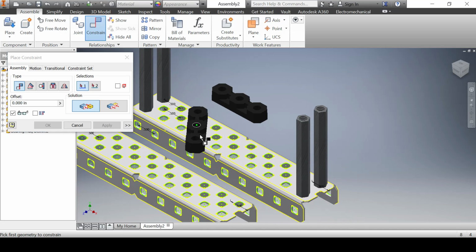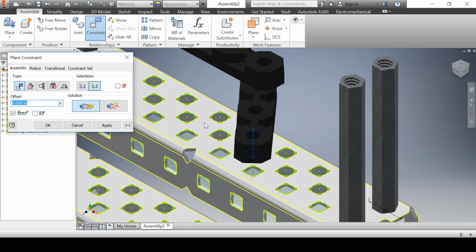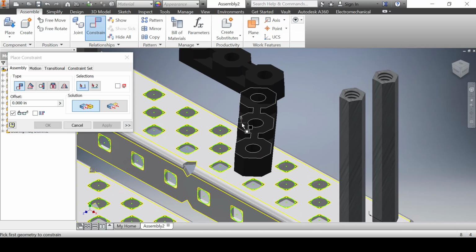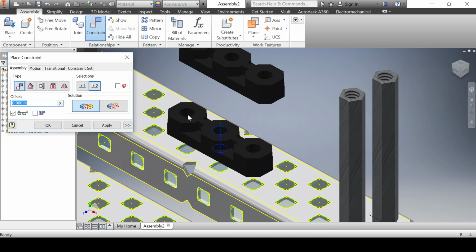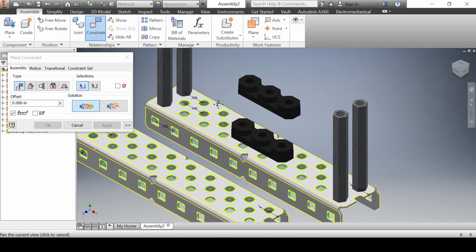Now clearly this is not the direction we want it. So what we do now, we take the axial there, constrain it with the axis there. Hit apply, and then just take a second point for a bearing, constrain it there. I could have done the outside one, I could have done this one and that one, this one and this one. Doesn't matter as long as you can get it to sit straight. So I'm going to apply there. So now my bearing's constrained.